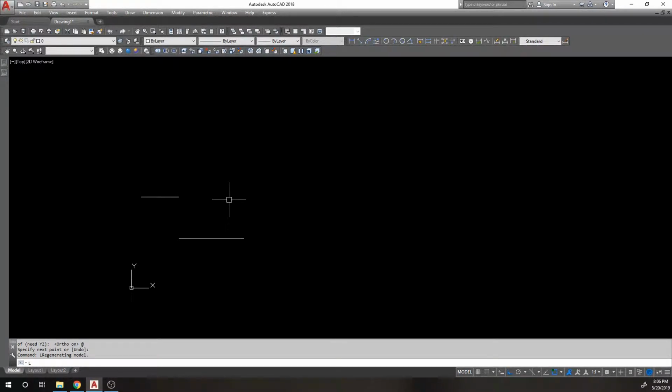So I'll do the y coordinate. Let's say I want to line it up with this. Well, with snap tracking, I would hover over this and you'd see a little invisible line. Instead, I'm going to use .y. I'm going to select or click on the end of this line with my OSnap turned on. And now I'm locked to that y coordinate. No matter what I do, I can't get any higher or lower than that y coordinate. Okay? And we're done.